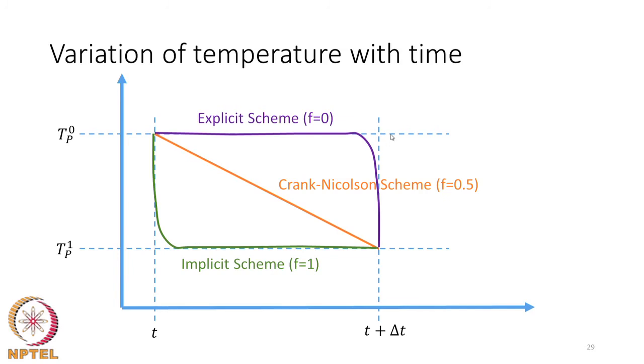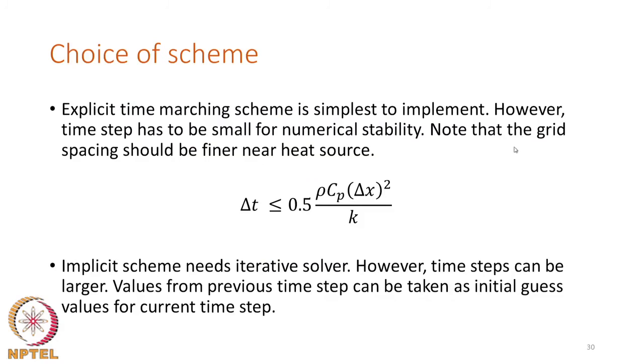And these three schemes have to be discussed before we adopt one of them for our solution, and generally one would use implicit scheme in these problems, because you do not have the time step problem whenever you want to do a long time simulation. And the reason why that is happening is as follows. Explicit time scheme is used whenever you want the program to be very simple, that is the source code writing is a very simple exercise, and explicit scheme can give you simple expressions and you do not have any iteration of the loops, therefore, the programming part will be quite easy.